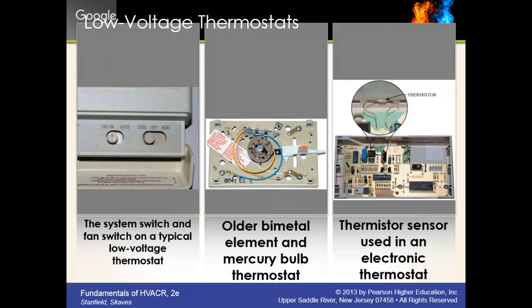But say you just want to, my analogy is that you've got a parking lot in your house and you want to blow the house out, you want to just turn your circulating fan on. Turn the fan switch to the on button. That's going to run the fan regardless of whether you're getting a call for heat or a call for cool. So it's always going to be on. Okay?